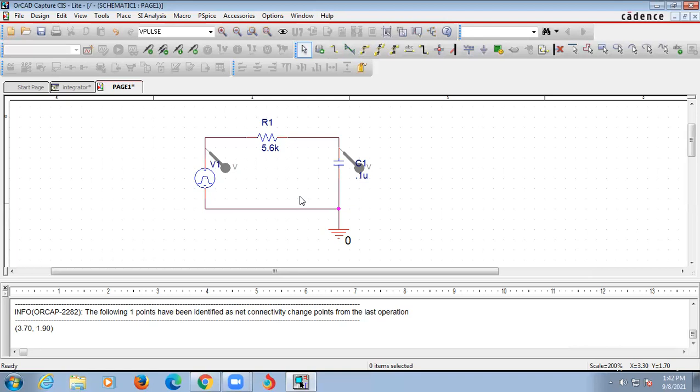So we need to label the net, or rename the net. Now the net name is N00200. This other one is N00156. This is very difficult to find in your simulation, so we need to rename these nets.